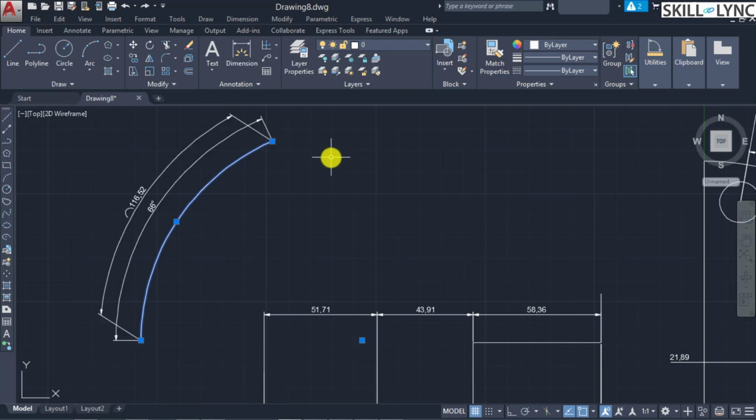Then in those cases, if it's difficult to dimension the part, we can use this jog radius dimension so that the origin point, instead of here, the reference is shifted to a convenient location. So towards this, we use this dimension jog command. On selecting the R for the circle, it prompts for the center location override. That is, we specify the new center.